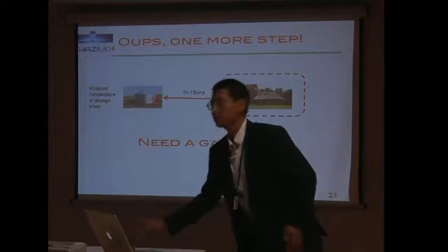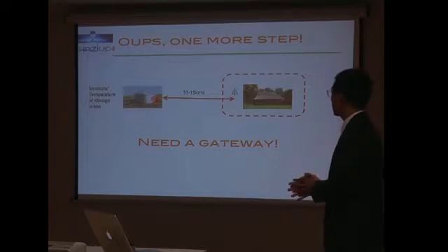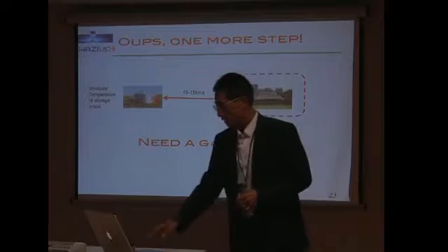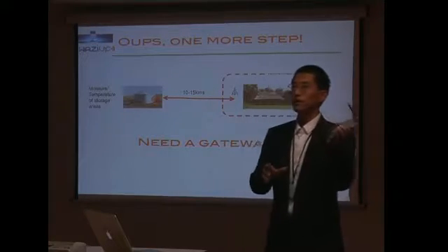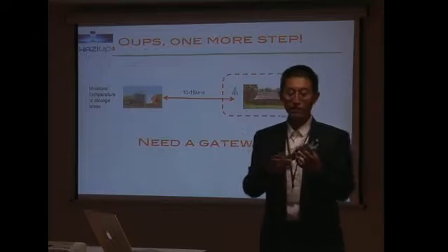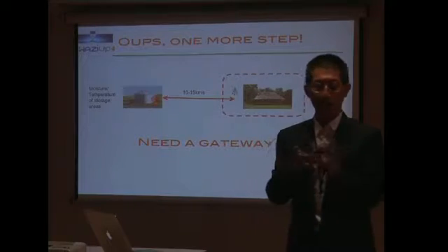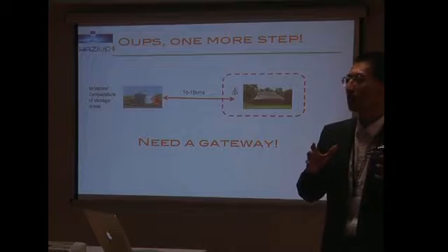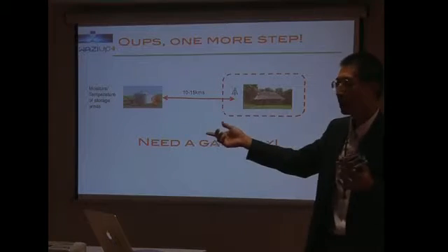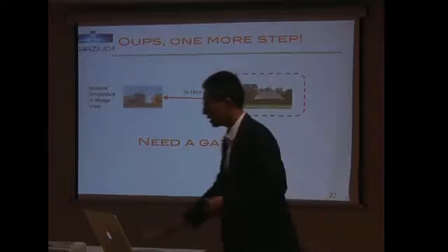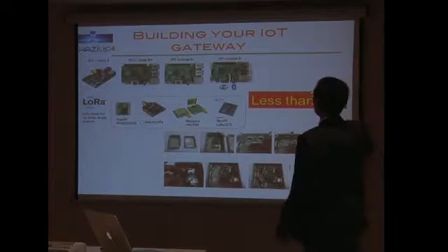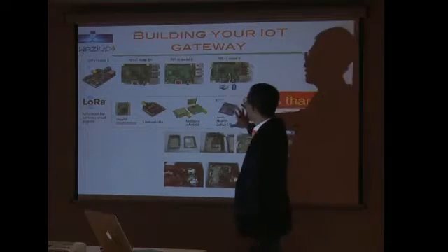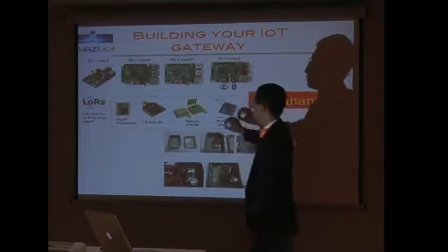And the whole system needs a gateway, of course, because this kind of radio technology means that you are sending from one device to a gateway. And you can have several devices, of course. You can have 200 devices sending to the same gateway. The gateway we are building is also a low-cost gateway because we base it on Raspberry, all models of Raspberry, using the same kind of radio devices.